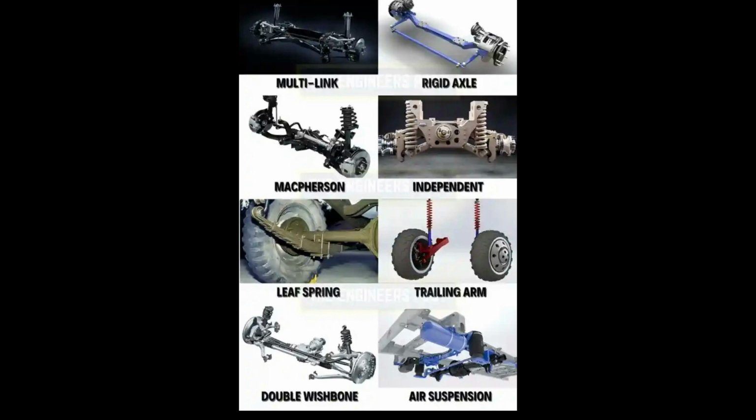Multi-link suspension. Multi-link is a suspension developed from double wishbone into a suspension that has a fairly complicated construction design because it has separate parts that are held together by joints. This suspension also has component ends that pivot on 2 sides of the arm. Construction is made by manipulating the direction of the force that will be received by the wheel.